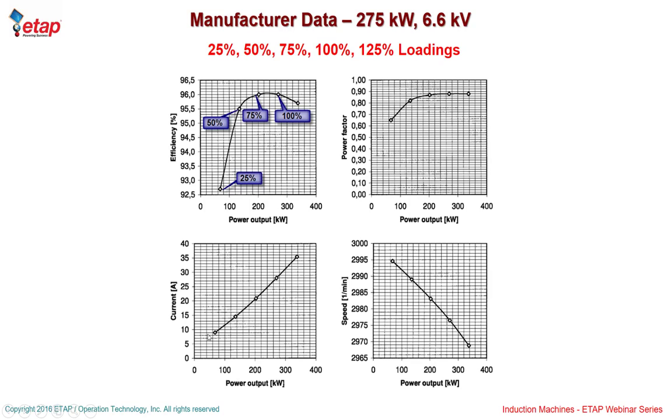If you want to get the current, for example, and your power factor at zero loading, you can extend these curves, but you have to have these curves from the manufacturer. Especially for larger machines, you cannot just go on and put typical values for really large machines.